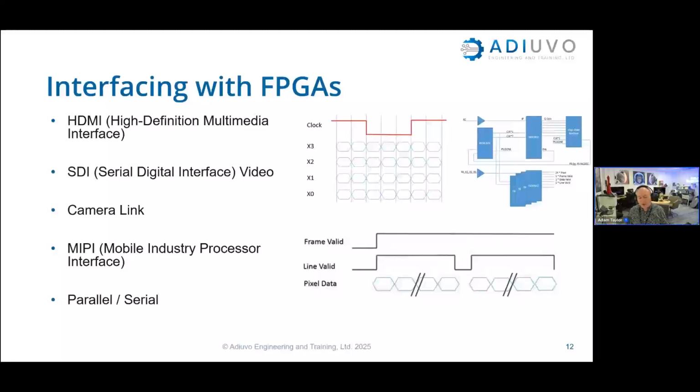One of the more popular ones that we see in a lot of applications, for example the sensor I was just talking about, or the example that's behind me connected to the Versal demo, is a MIPI camera. MIPI is the Mobile Industry Processor Interface, and it's only really designed for going about 30 centimeters. It's not really designed for long runs. You can make it go over long runs with things like GMSL, which take the MIPI, convert it into a coax, and then convert it back into MIPI for connection to the FPGA. That's really popular in automotive, aerospace, and defense type applications.